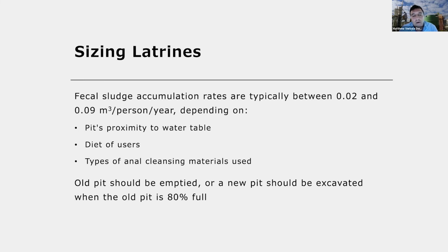General rule is that when a pit is 80% full, it should be covered, its use should be discontinued, and a new pit should be excavated, or the old pit should be emptied so that it can be used again.